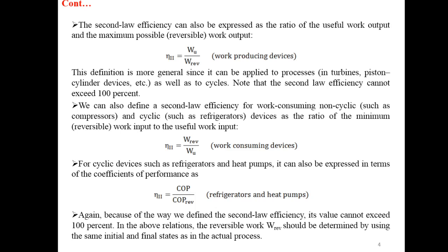We can also define a second law efficiency for work consuming non-cyclic devices such as compressors and cyclic devices such as refrigerators, as the ratio of the minimum, that is reversible work input, to the useful work input. This is valid for work consuming devices such as refrigerators and air conditioners.